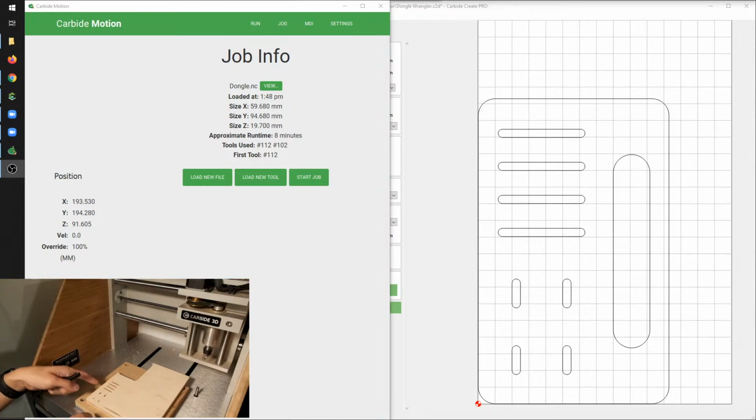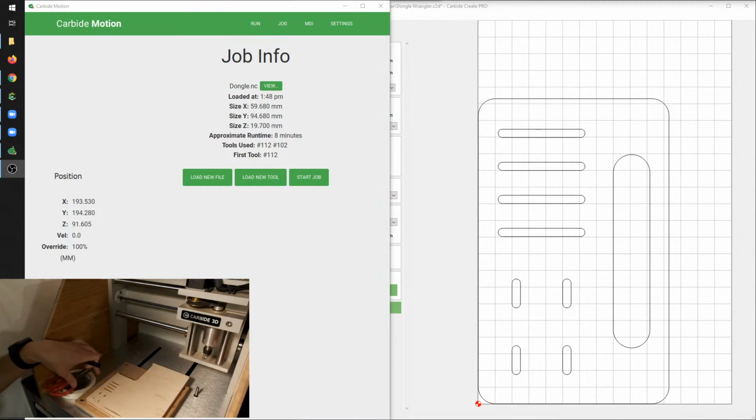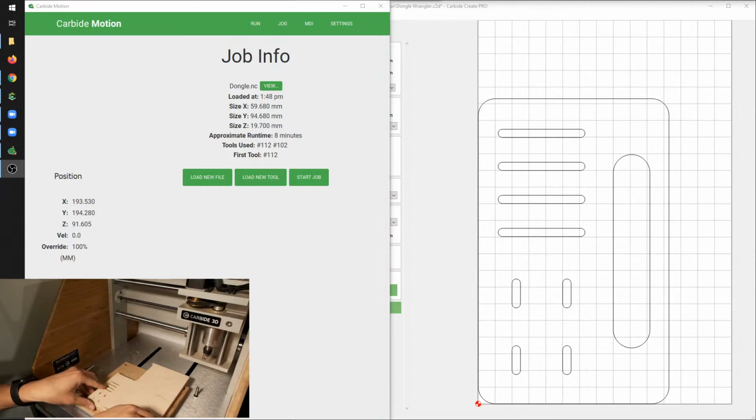I just want to make sure that if I throw some more tape down on here, because the 1/8" toolpath is going to be significantly more violent, and that's what might dislodge this piece. So I definitely have to put more tape on here. What I'm going to do, just to make sure I don't lose my 0 when I reposition this, is I'm just going to mark down where my stock previously was. You could also tape down some blocks or clamps here as a fixed reference, so that when you pry your workpiece off, you can just butt it up against there again.